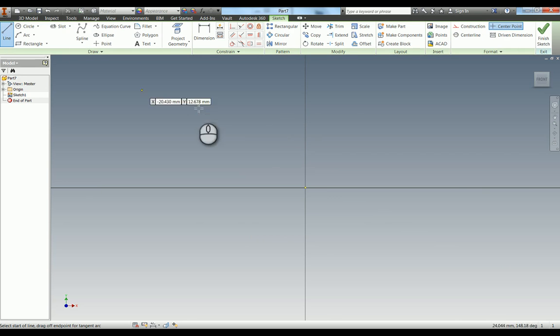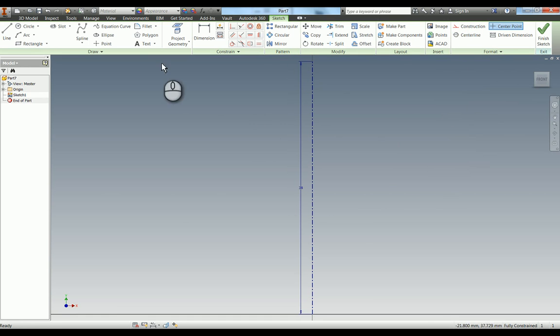With a revolve, the first thing we want to do is put in a centre line. It needs to be at least the height of what we're going to revolve. And you'll notice it didn't change the format of the line, but with Inventor that's fine, we'll change it afterwards. I'm just going to fit to page. Now I'm going to start doing the sketch geometry. So as with everything else on Inventor, we keep our sketches nice and simple, and we'll detail it afterwards. So there we go.